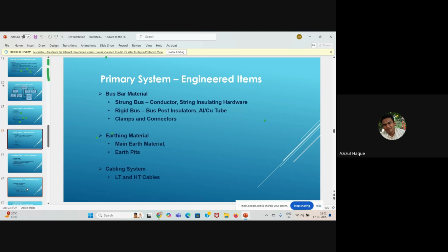So for designing this connector, I first need the detailed drawing of the breaker from the vendor I am taking it from, and I have to find out how the terminal pad is designed. Accordingly, I design my connector so that it connects the aluminum tube to this breaker.